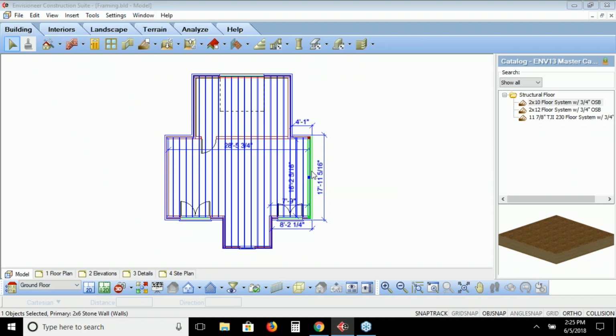So to be able to select the floor, I'm going to cycle select through the options that are also ending with this wall. Once I select this wall, I'm going to hold down the Shift key on my keyboard and scroll with the scroll wheel on my mouse. As I do that, you can see that it's selecting different things. I'm going to draw your attention down to the lower left corner of the screen, where you can see that it's constantly changing some text down there.